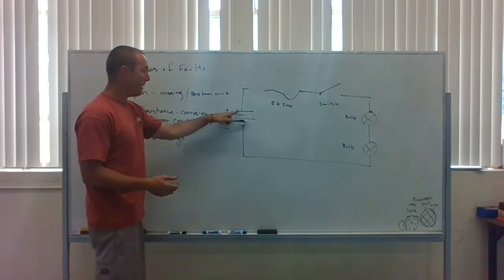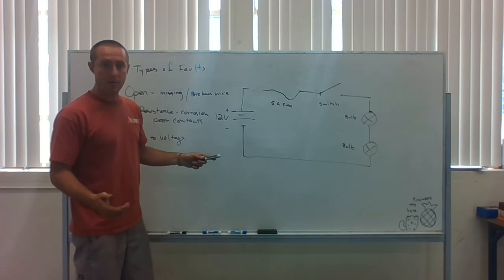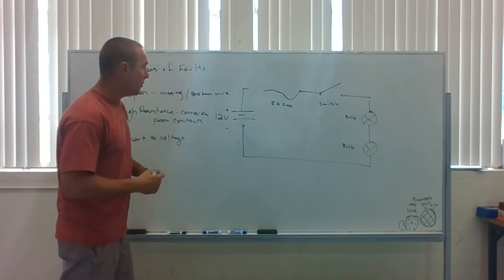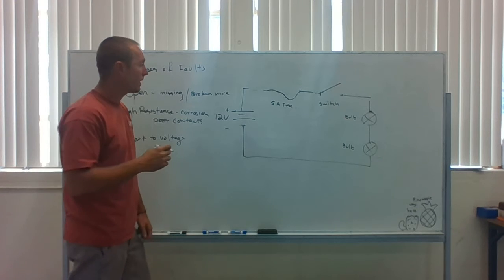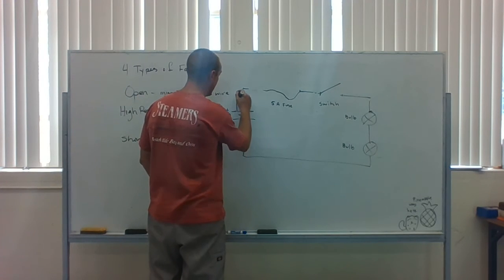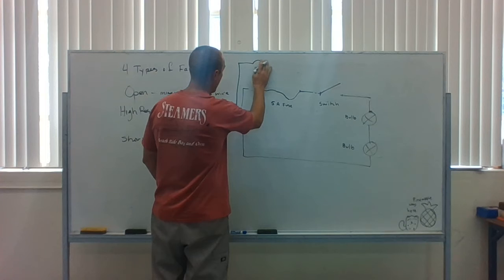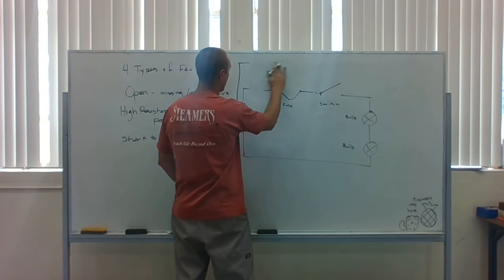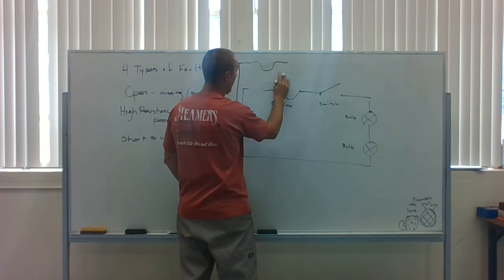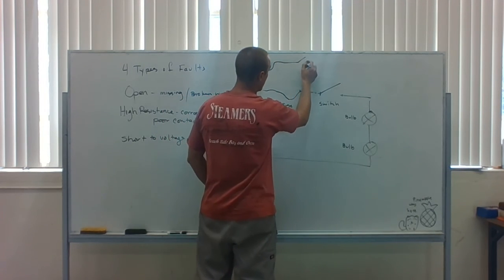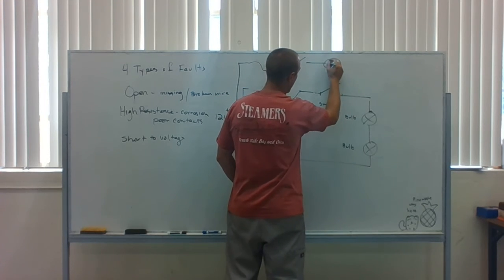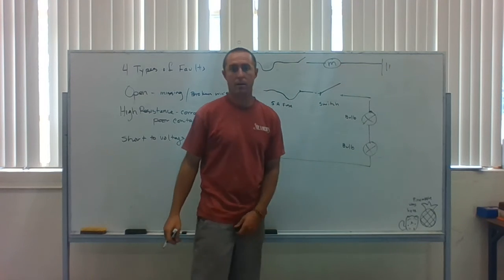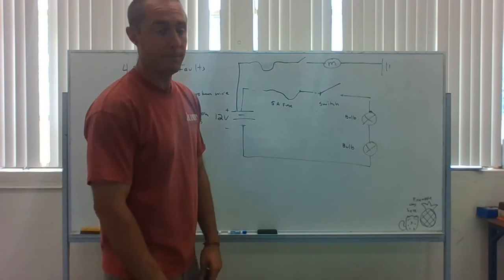So we know from our battery or from our alternator, we're going to have a wire harness and it's going to go everywhere in the car. So we have a bunch of stuff right there. Well, let's say I'm coming off of here, separate circuit. I have my fuse. That's a horrible fuse. Let me see if I can improve that. All right, I have my fuse, I have my switch, and I have my blower motor for my car. I have my AC blower motor.